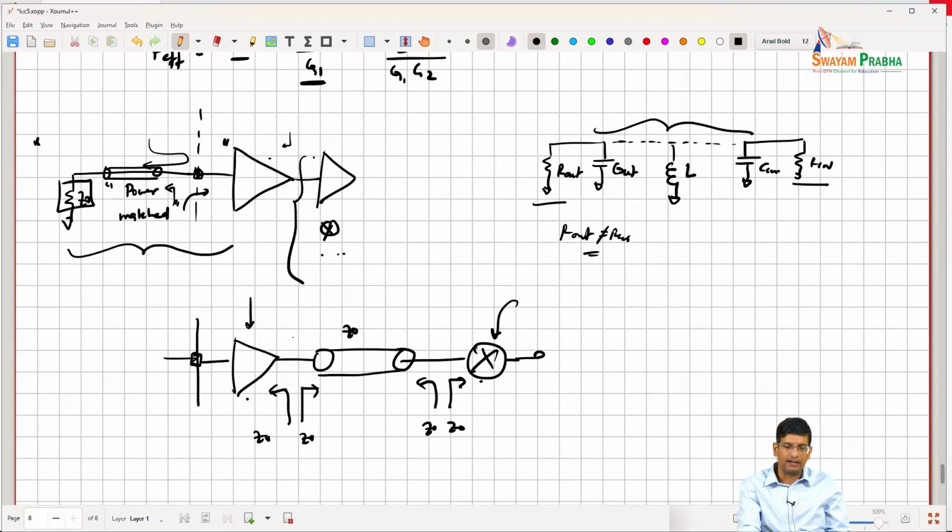If I can guarantee placement of the output and full knowledge, or I start designing in a cascaded way where I first design the mixer, then I know the load, I know where I'm going to place this, and then I'm going to design the LNA, design it in voltage domain without conjugate matching, by all means. It will work. That will not be a problem.